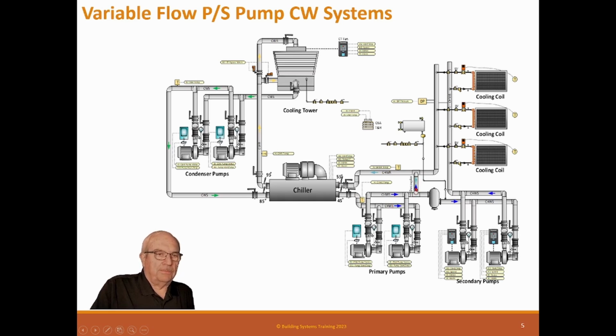This is the decoupler. This is the problem child. This flows in two different directions. You notice when the primary has more water, it flows in this direction. When the secondary has more water, it flows in this direction. And that is the secret to not have it wrong.